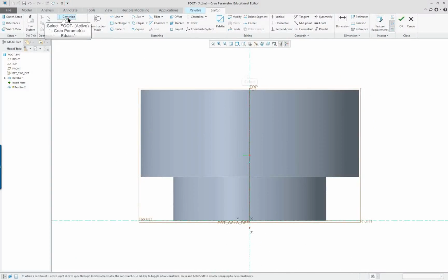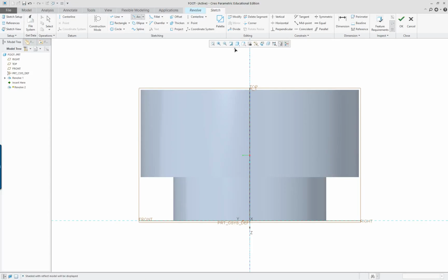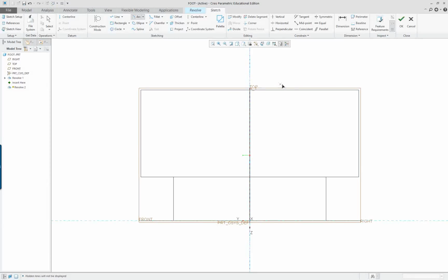And again, I'm going to put in a center line. The other center line is not there. This is a new sketch. It's like a new sheet of paper. And there's my axes. And in this case, I think I'm going to do an arc and center ends. And I'm also going to go, I'm hitting my control key. This is new for 4.0. You can get that obviously from your display style. And I'm going to have the arc center ends.